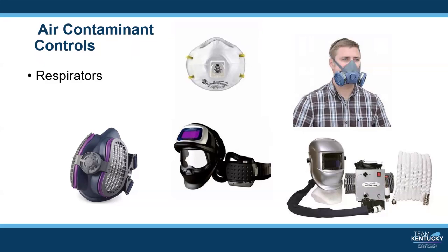There are specialized respirators designed to fit under a welding helmet, if you see the picture on the bottom left. There are also specialized welding helmets with built-in respirators. When welding with certain especially hazardous metals, a powered air purifying respirator, PAPR, might be required.